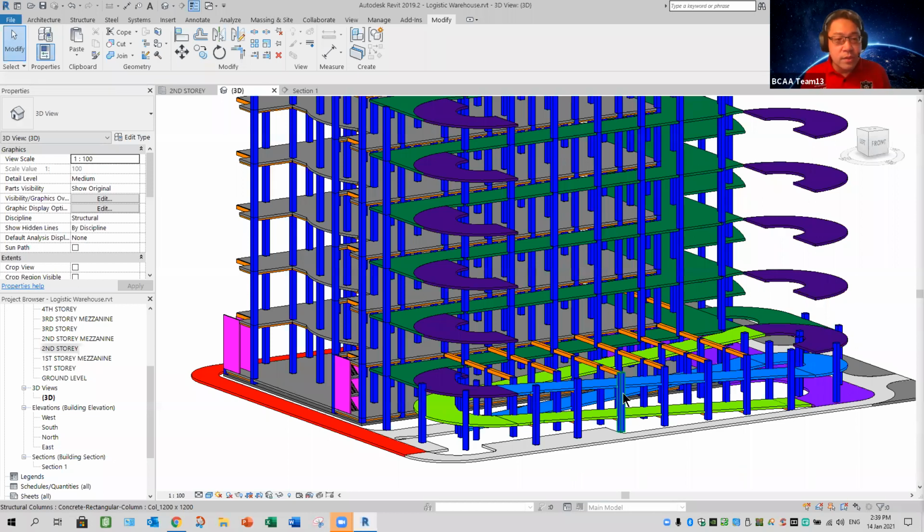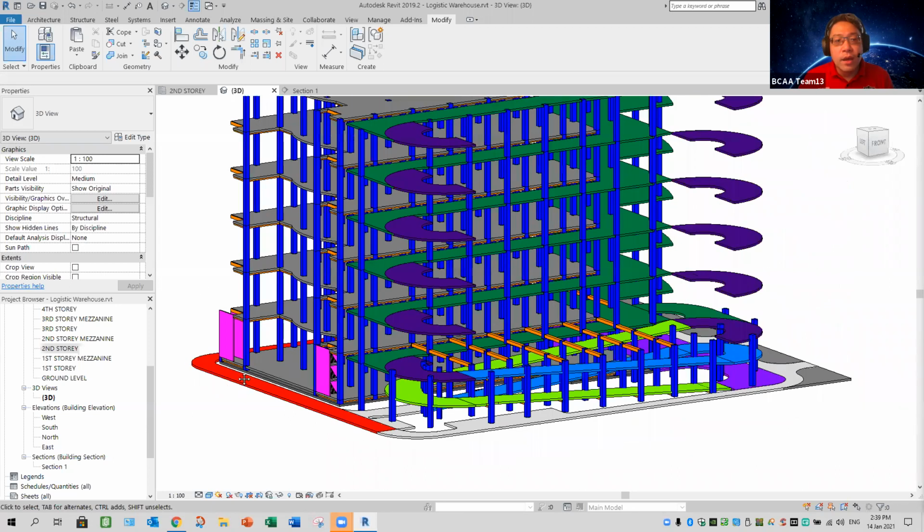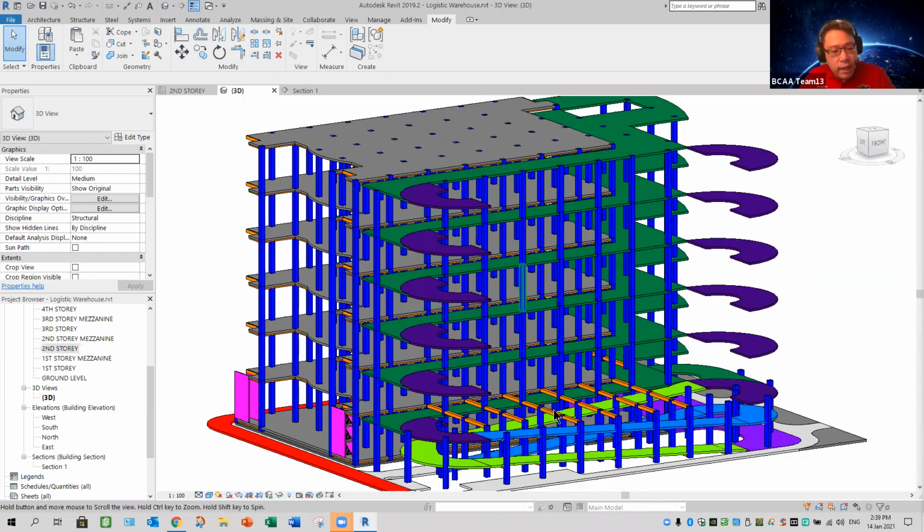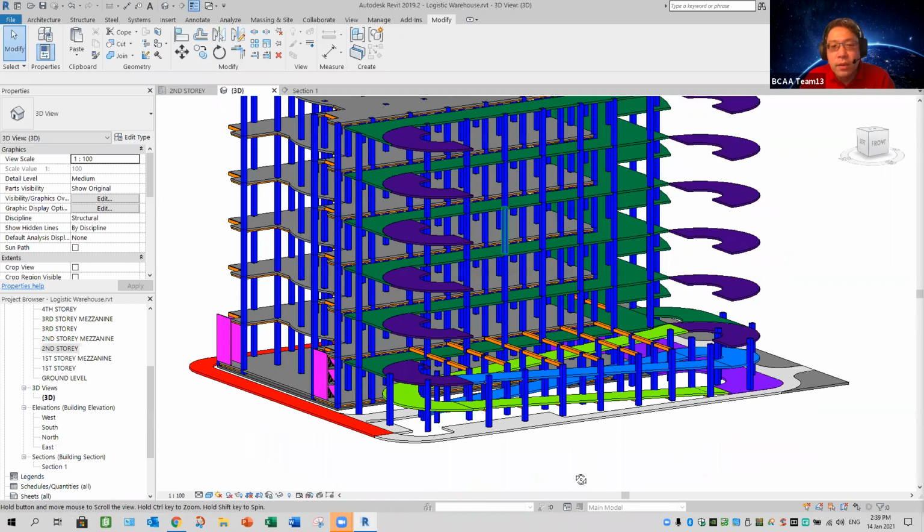This is very ironic. Yeah, it's very weird, but it does happen. I've tried a lot of times, in different versions, all giving me different results. Now in 2019, I tried to copy multiple levels in 3D. All the floor plans go even higher, a jump in level, which is quite misleading. Okay, yeah, you copy level by level, you're safe. You copy more than one level, the whole thing goes haywire. I don't know why. So do one thing at a time. Don't be greedy. All right.